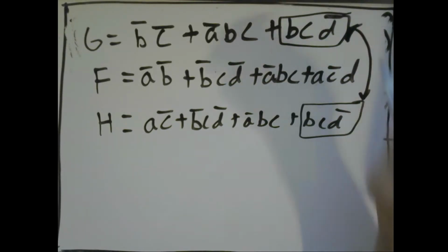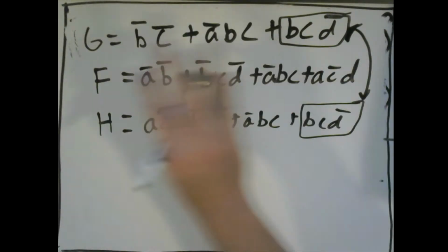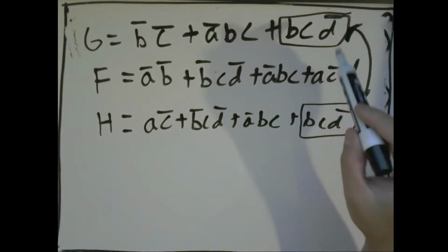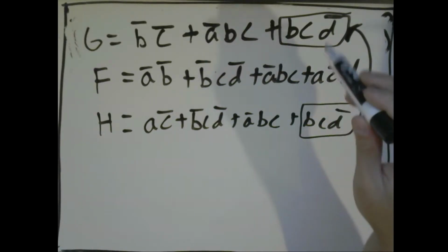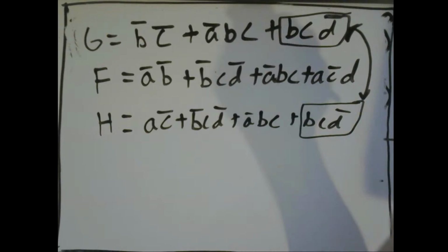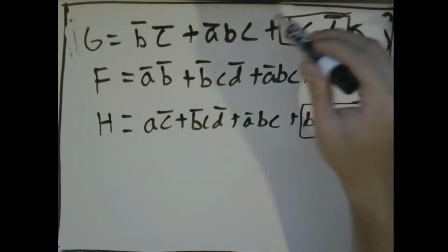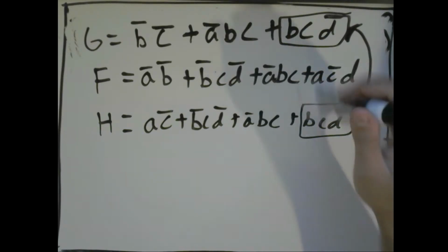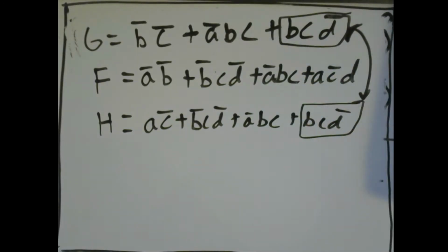So if we were to do a real circuit, we could write all these as separate, but we see that we're calculating the exact same thing twice in both equations. So if we went out to make a physical implementation of the circuit, we could just write one of these gates down at step 2, right? Because they both have the same inputs. It's the same gate. So that's how the sharing works.